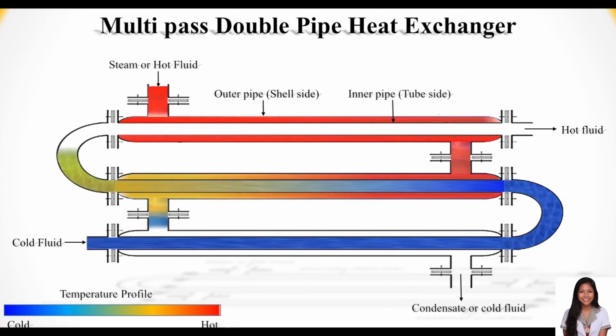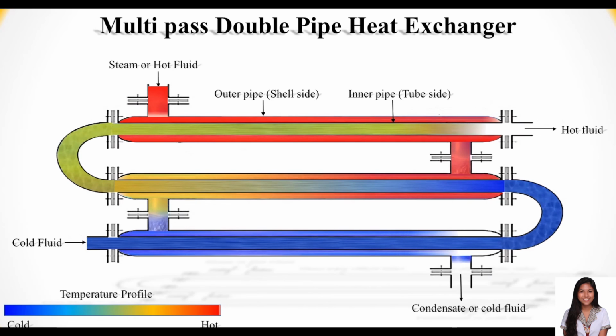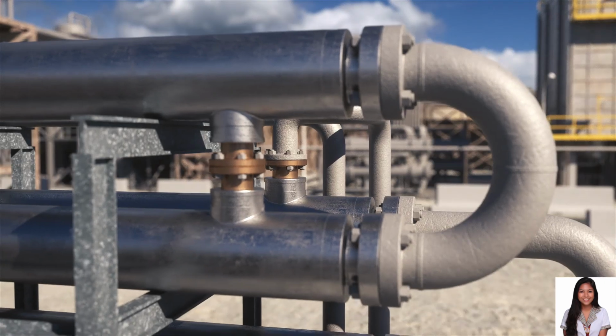Whereas the counterflow heat exchanger has three significant advantages over the parallel flow design. First, the more uniform temperature difference between the two fluids minimizes the thermal stresses throughout the exchanger. Second, the outlet temperature of the cold fluid can approach the highest temperature of the hot fluid, or the inlet temperature. Third, the more uniform temperature differences produce a more uniform rate of heat transfer throughout the heat exchanger.